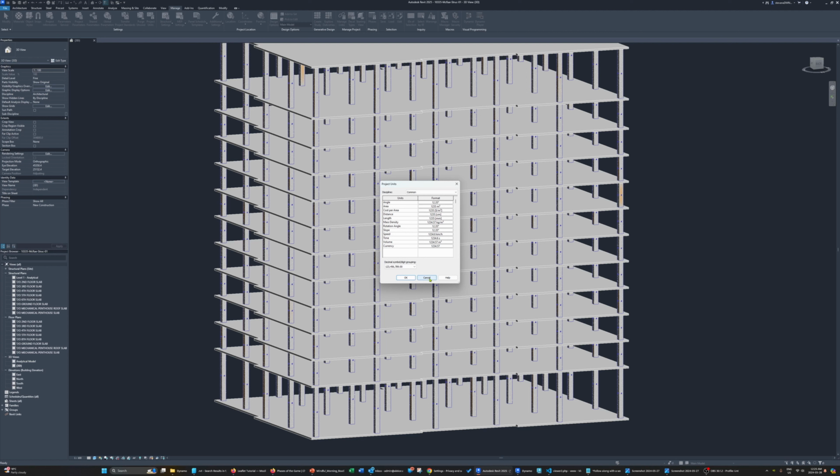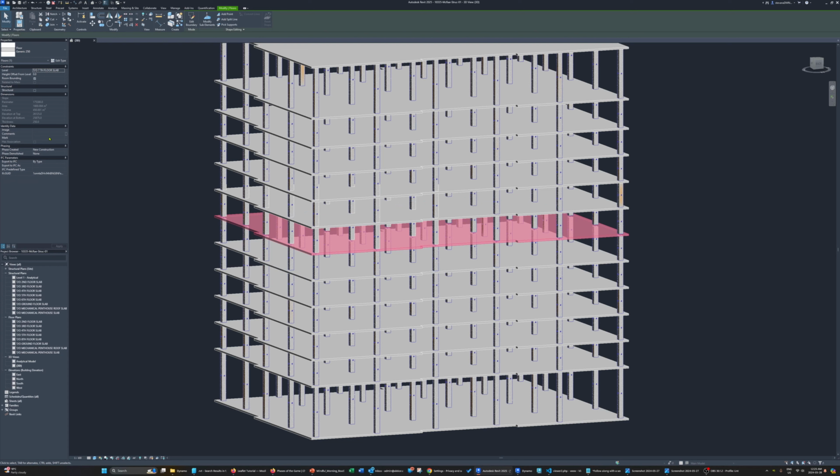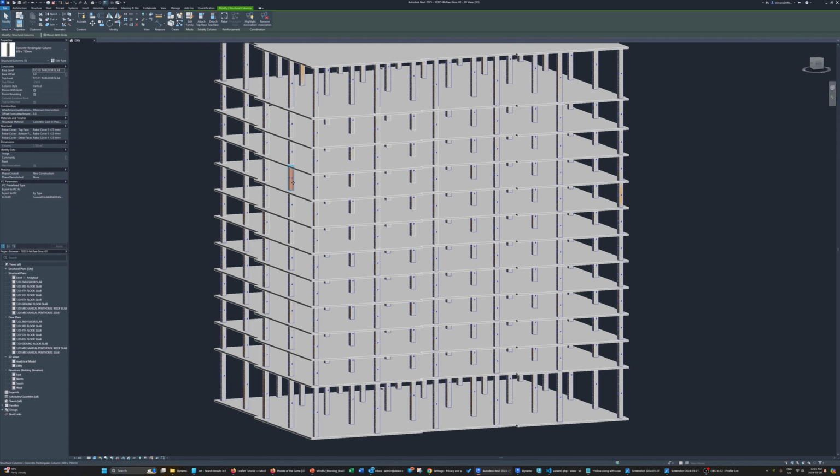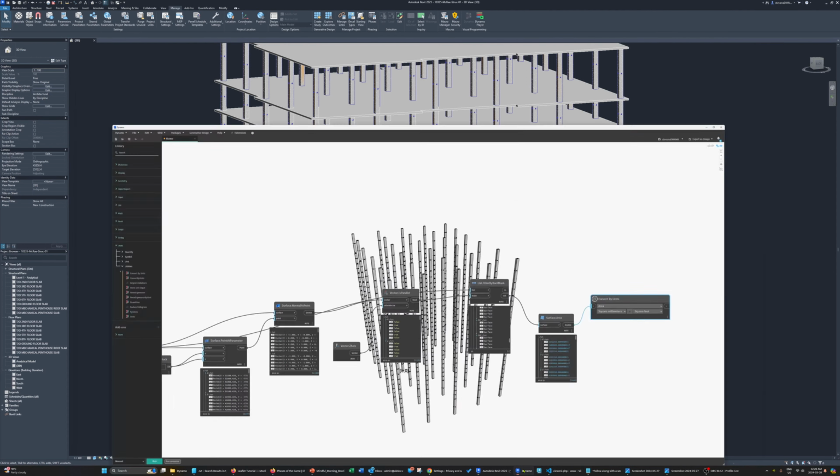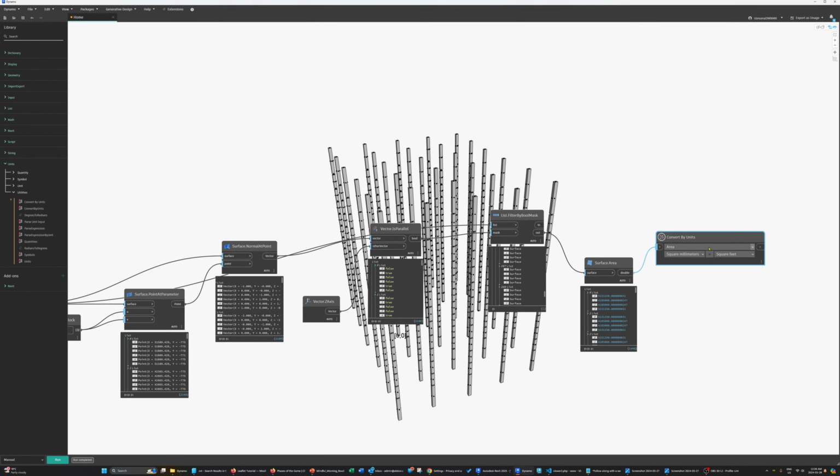That being said, most likely my area, we can see here it's in meter cube, but ultimately what I'm getting is not the meter cube. The reason is because I'm extracting these and the unit type is in millimeter. So what I'm getting ultimately here are square millimeters, and I need to convert this into square feet.